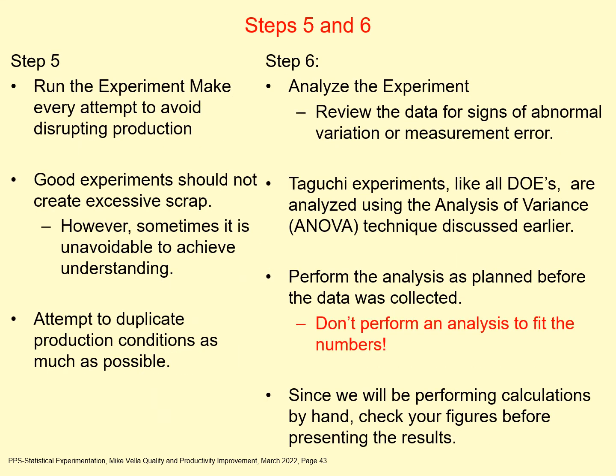Step 5 and 6. In step 5, we're actually going to run the experiment and make every attempt to avoid disrupting production. Good experiments should not create excessive scrap. However, sometimes it is unavoidable to achieve understanding. Attempt to duplicate production conditions as much as possible.